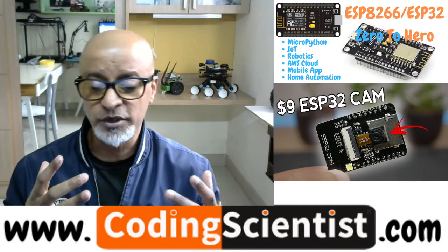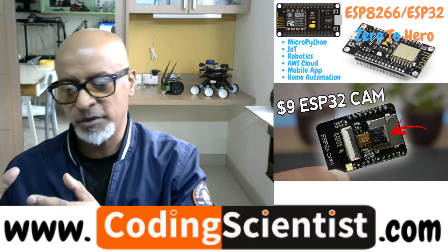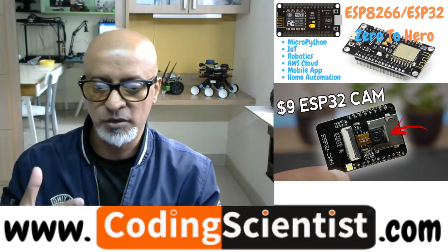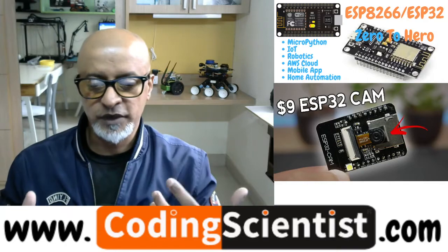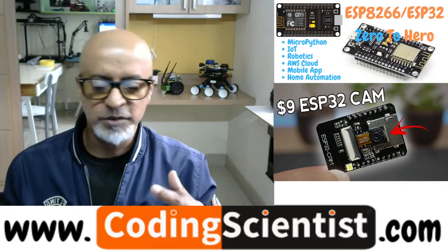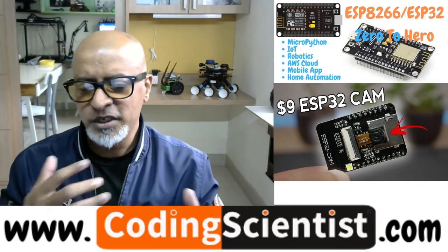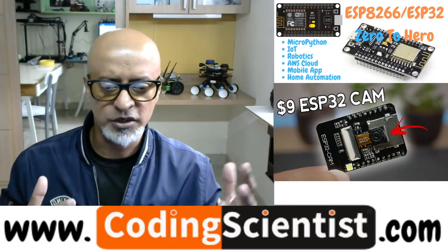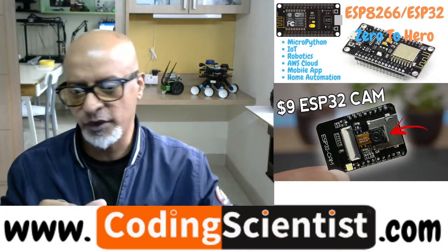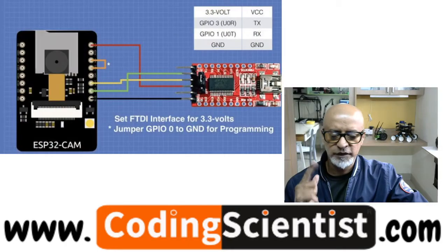The ESP32 CAM basically hosts a web server which has been modified from the example code which came along with the bundle when you install the board manager, right? So we can modify that code and make it use the same web server to attach your GPIO pins and control the motors by sending out the signal. And it will basically create four different buttons in your HTML, simple buttons in the web browsing window.